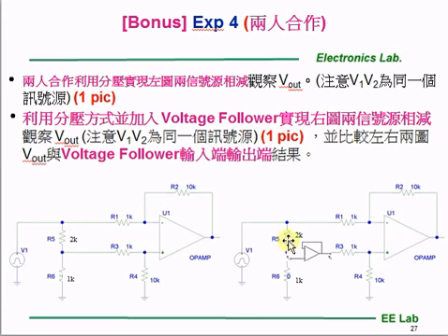However, if we utilize the op-amp and connect it to form a buffer, then we need only consider the voltage dividing circuit. The buffer has the characteristic of large input impedance and provides almost zero output impedance. Therefore, it can transfer the voltage almost ideally from this point to here and become the second signal provider that we needed. That's all for this lab.